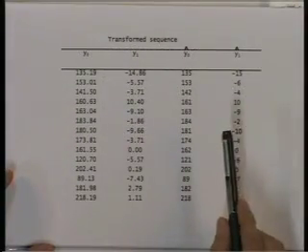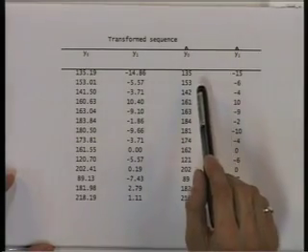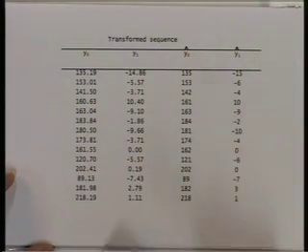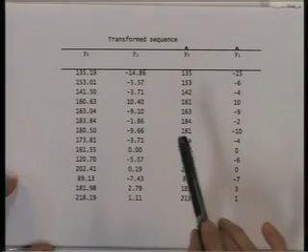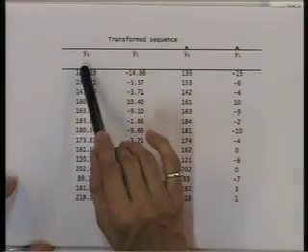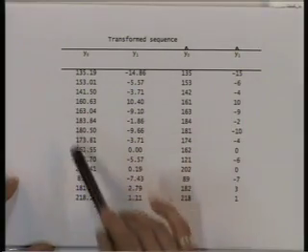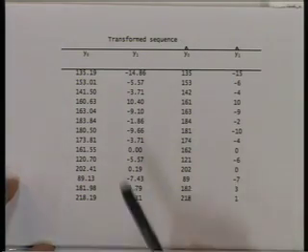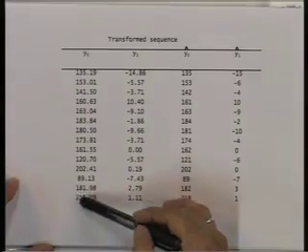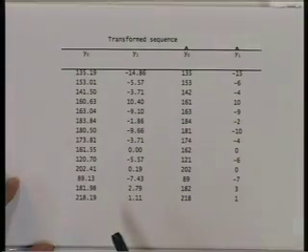Now, if we did that, we are not gaining any real advantage from the transform coding, except for the fact that earlier we would have quantized the x0 and x1 samples, but now we have quantized y0 and y1 samples. So, if we want to gain the real advantage from transform coding, then we should exploit the characteristics of y0 and that of y1.